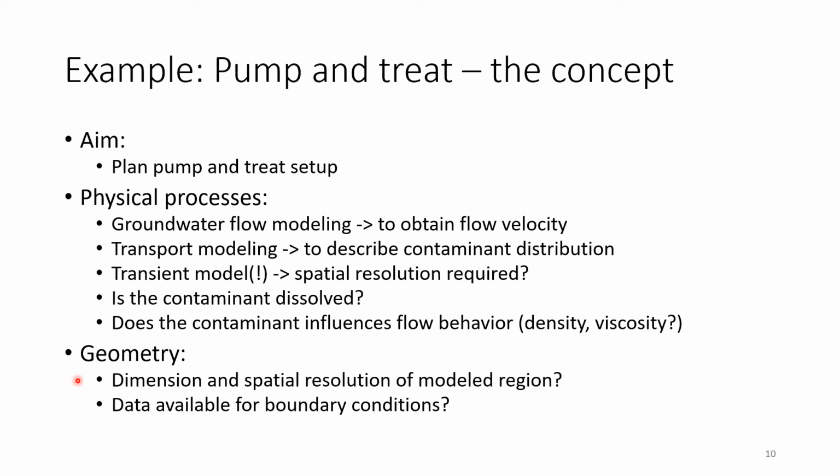But then again, we already talked about, for example, spatial resolution up here. We were talking then about the geometry when setting up the model. How large does it have to be? It depends on the flow velocity as well, right? And the time frames I'm looking at. Do I have enough data for my boundary conditions? So in the sketch I showed above, there was a pretty good database, but sometimes it's suitable to extend, for example, my model domain, because then I have good information on the boundaries due to some wells or whatever, right?